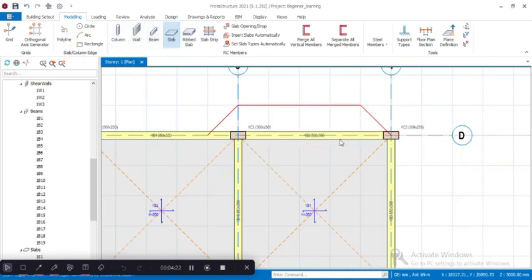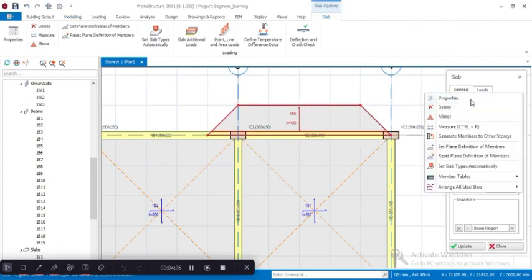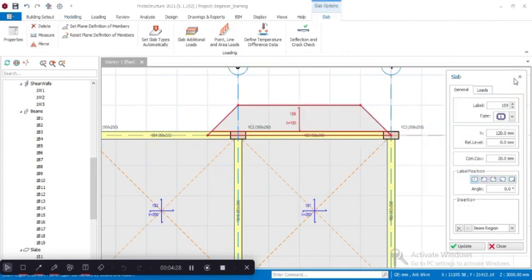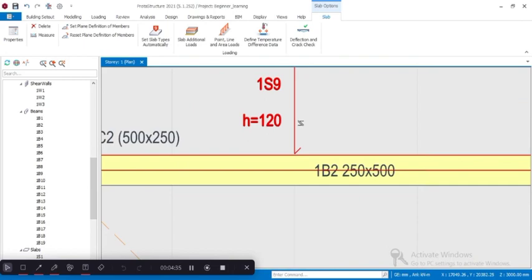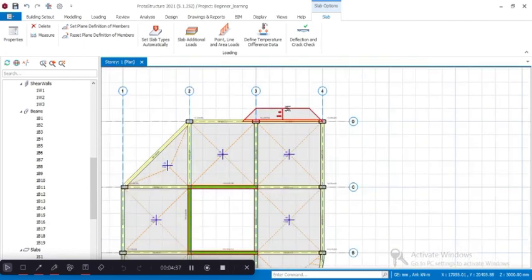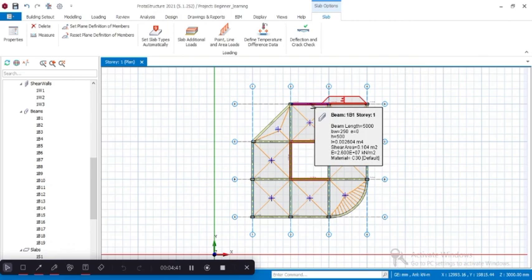So I'm clicking on the slab icon. Place it in. And that's it. So here we have our cantilever slab. Now you can see the final thing here. Okay, so notes for regular cantilever slab, it is recommended to use type 12. So type 12 on the slab, you see it is cantilever instead of the slab edge line.